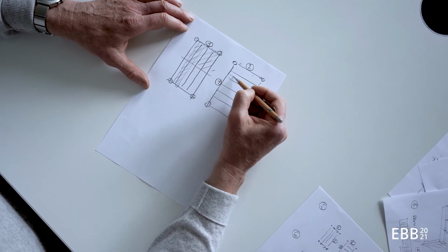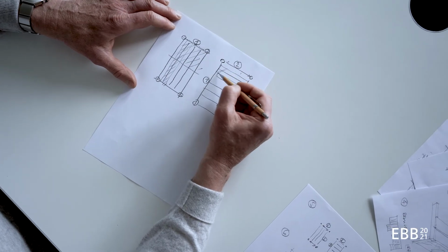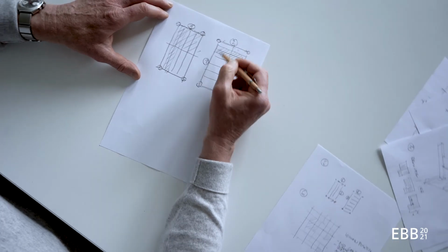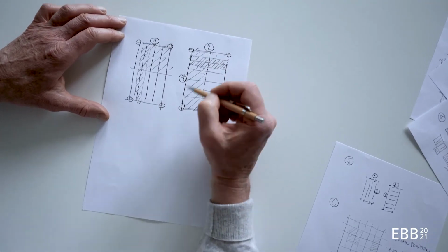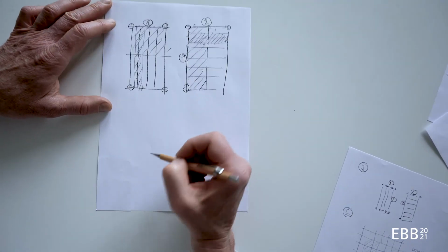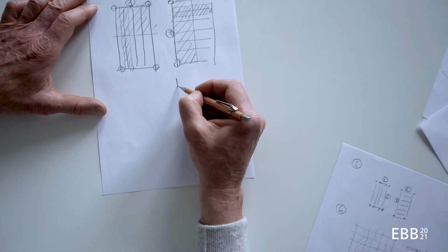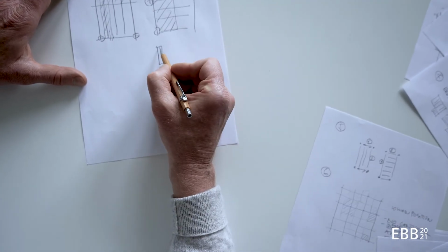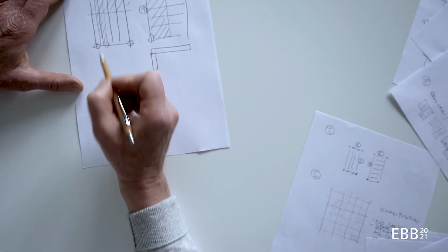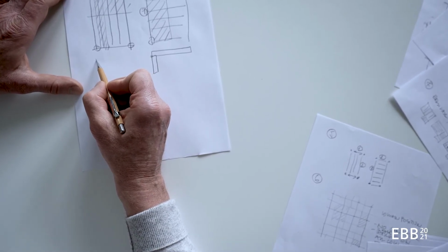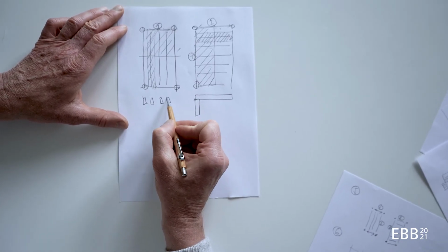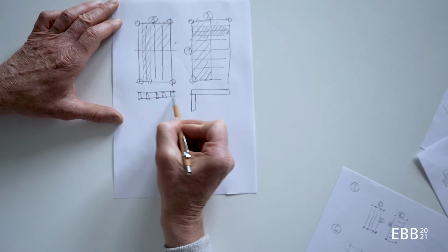But it will get only 1/6 of the load, while this one here gets half of the load as before, and its span is much wider, so it's supposed to be much higher. So if I draw a section here, this will be rather high, the secondary beam will be not so high, and here the primary beam and the secondary beams will be more or less the same.